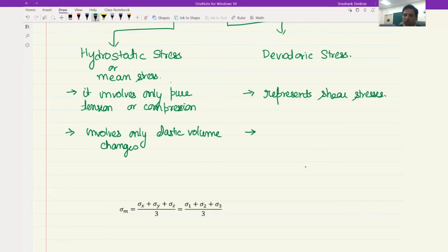On the other hand, shear, which is basically shearing of the plane of atoms, and this stress is what leads to the breaking of the bond, and hence generation of the dislocations, a concept that we will visit very soon. So this is the one which actually leads to or causes plastic deformation. So this is important for plastic deformation.